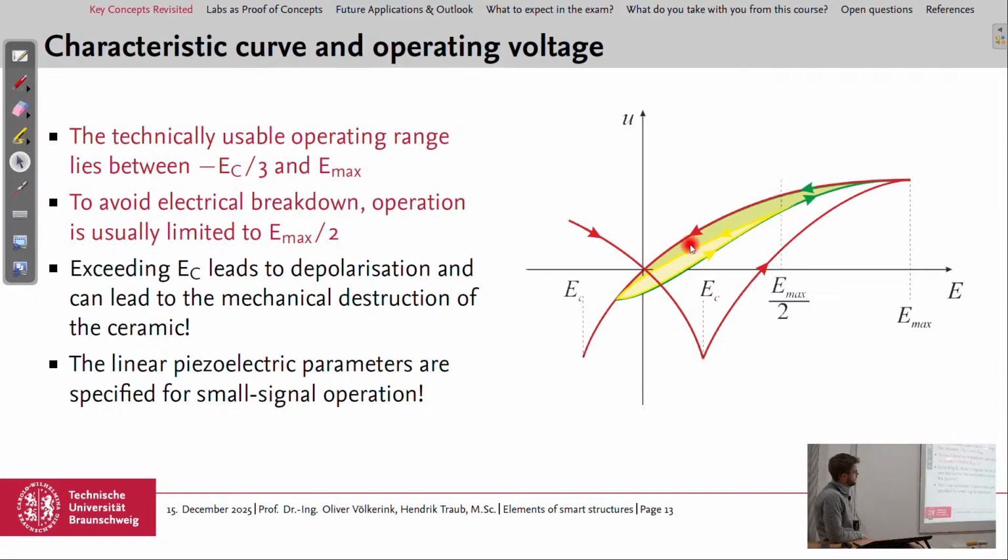And so the technically usable range is marked here in yellow, and for our simple analytical modeling of the piezoceramic effect, we assumed small signal operation, which would be a straight line here in this operating range.